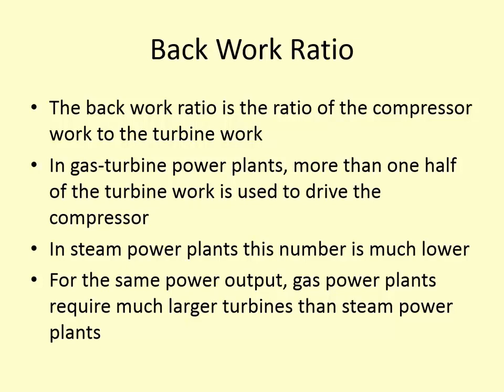So boundary work is PdV. Pump work has a V and a P in it, but they're not the same. VdP. So this specific volume for a liquid is much lower than it is for a gas or a vapor, right? So in a compressor, we're compressing a vapor, which means our specific volume is much higher, which means that the compression process requires a lot more work than it does if you're pumping a liquid.